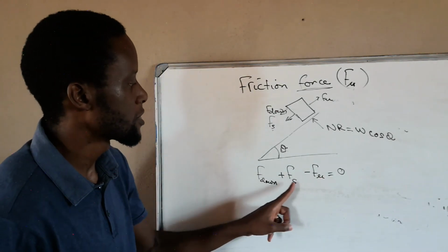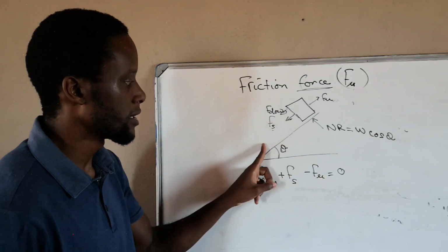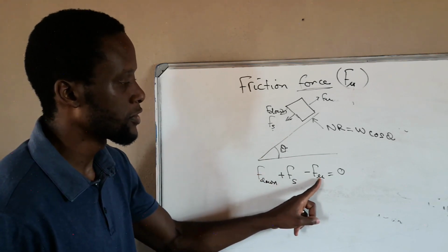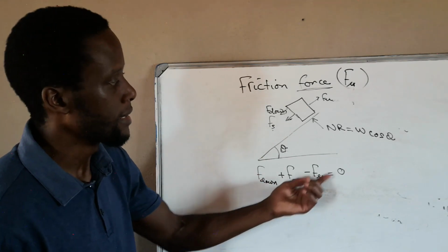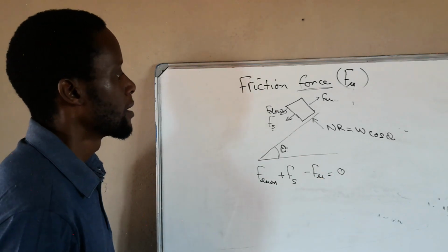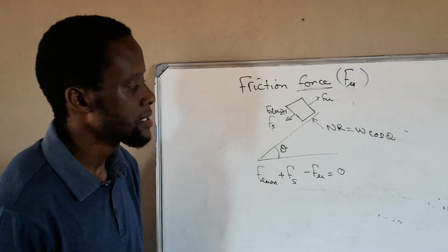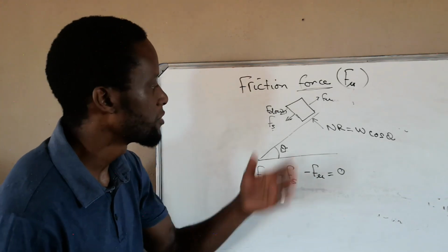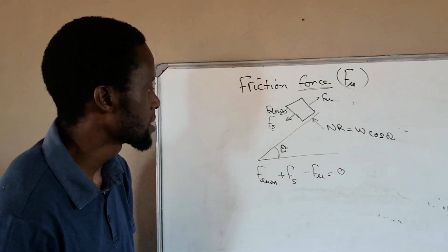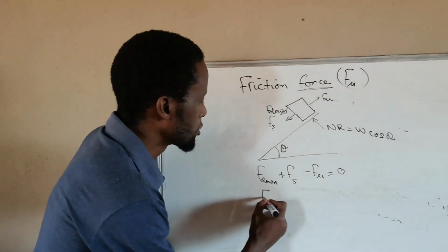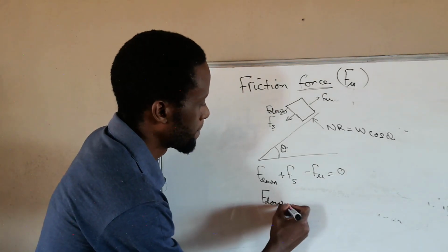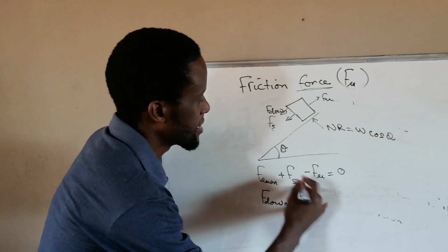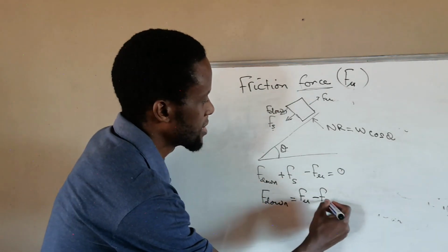This is our friction force, sliding force, going in the downwards direction, your downwards movement. So these two are working together. Friction force is the one that is opposite. Then everything should be equal to zero. Yeah, so basically this is what we'll be doing, and you calculate. You can simplify this if you want to say, okay, how much force do we need to go down? Therefore, our friction force goes to the other side. This guy goes to the other side, our sliding force.